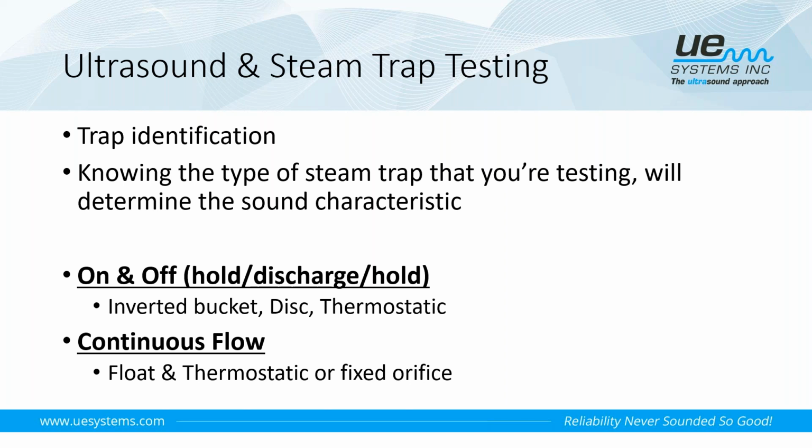And then typically within a few seconds or a minute later, we'll hear the trap cycle open and then we'll hear it shut. So again, your inverted buckets, your disc style traps, two very common styles of traps, thermostatics, those all operate on that hold, discharge, hold operation.